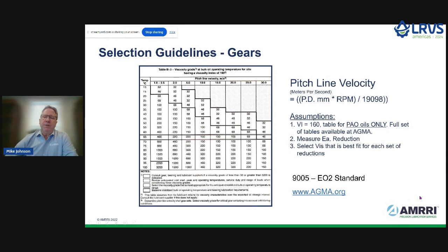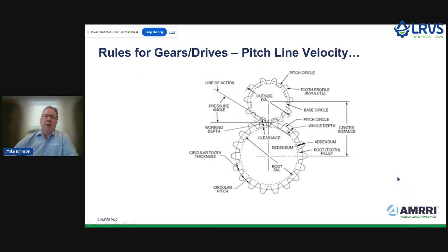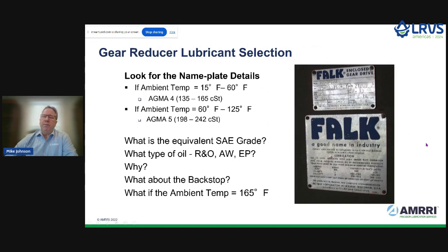Very objectively definable. Fortunately, our gearbox manufacturers have done a good job of defining this and putting information on nameplates that go on our gear drives. They've done that for us. The pitch line velocity is the speed that this dotted line is moving in circles. The pitch diameter between the 2 gears is the point where load is transferred and rolling contact occurs. So that's the critical value.